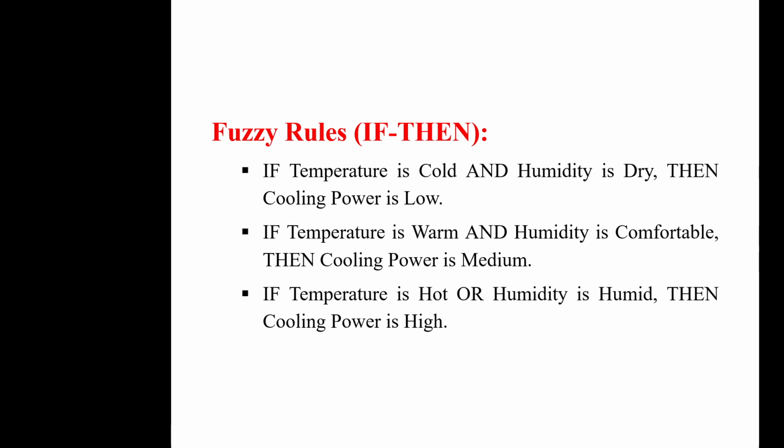three rules. The first rule goes like this, and I've told the class that in the development of fuzzy rules, we use an if-then statement, and the statement in between if and then is referred to as the antecedent, and anything after then, that is the decision that the inference engine is going to come up with, is what we call the consequence.